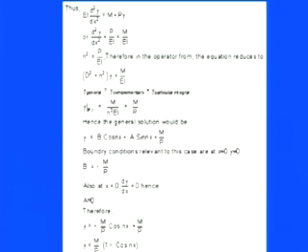So we need to convert this into the operator form. We have (D² + n²) y = M/EI. You see there are two main parts: one is the complementary function, and the other is the particular integral. The y_PI is nothing but M/(n²EI), which equals M/P. So with that we can simply replace this in terms of the complete solution.